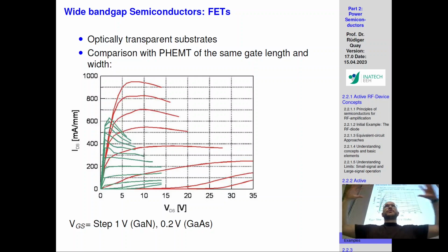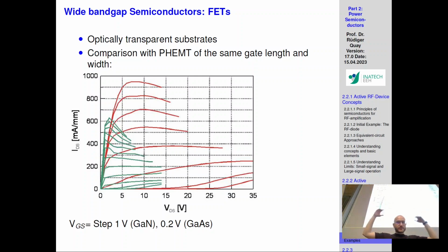So these large tube amplifiers, not semiconductor devices that are mounted. But for lower frequencies, 20, 30, 100 gigahertz, 200 gigahertz, 300 gigahertz, you do have power amplifiers that are semiconductor based. And for these cases, you can see that having something with a higher band gap allows you to apply higher voltage, and applying higher voltage means higher power.